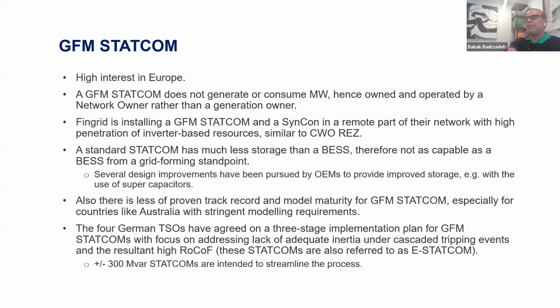One of the experiences with grid forming STATCOM is that, and this surely will change in a year or two, at this point in time, in terms of the proven track record and especially the model maturity, we're talking about EMT modeling or phasor domain modeling, because the only way that a TSO or ISO can design and control these devices is to perform simulation studies on their wider power system and see what the problems are and how these devices can be controlled to address those problems. And especially I'm talking about a country like Australia that has a stringent modeling requirement, and like most of you, or all of you, based in the US, I assume. So obviously with NERC's initiative, the US is also moving on a similar trajectory.